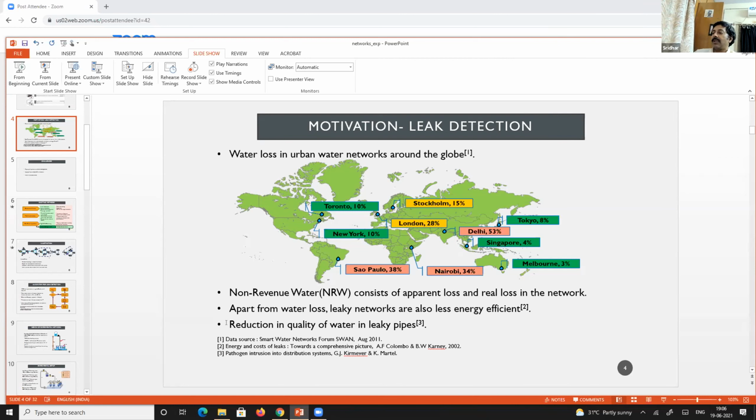But in cross-country pipelines they implemented this, physically simulated a leak, and using available pressure and flow measurements, since there is a lot of incentive for both supplier and consumer to put up flow meters, they were able to isolate the leaks to a section of the pipeline, up to a few meters, if I remember right.